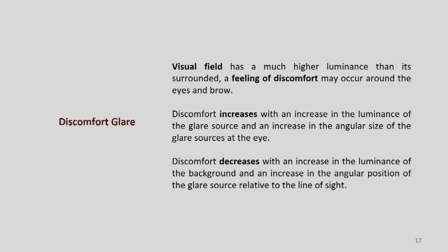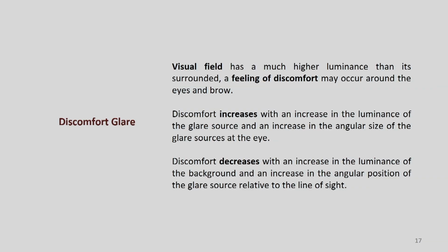Discomfort keeps on increasing if the luminance of the glare source increases, and the angular size of the glare source at the eye level increases. If that happens, your discomfort level keeps on increasing, but it will decrease with an increase in the luminance of the background, not of the source, and an increase in the angular position of the glare source relative to the line of sight.